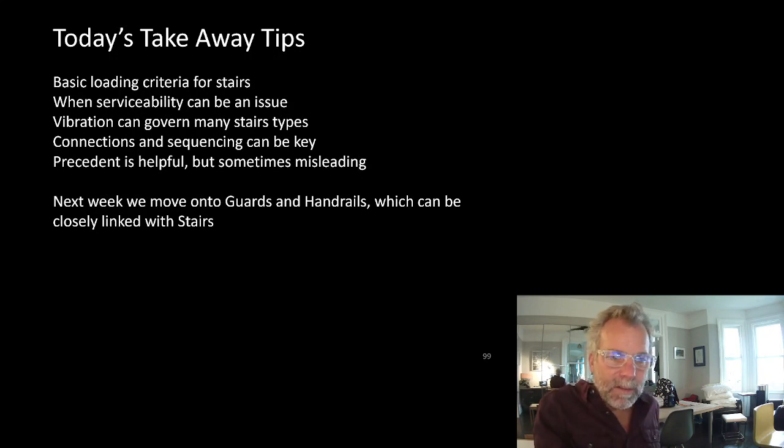Serviceability is almost always the governing criteria for a stair, whether it be straight sag or vibration. Vibration is very, very often the key. Shannon talked about it. The 1 kilonewton, 1 millimeter is a really sound rule of thumb that is indicative of vibration performance. Keeping under 1 millimeter for 1 kilonewton for a stair with a low inherent frequency is probably not enough. We're not necessarily going to get there, but it's highly indicative. And for a stair with a high frequency, it's fine.